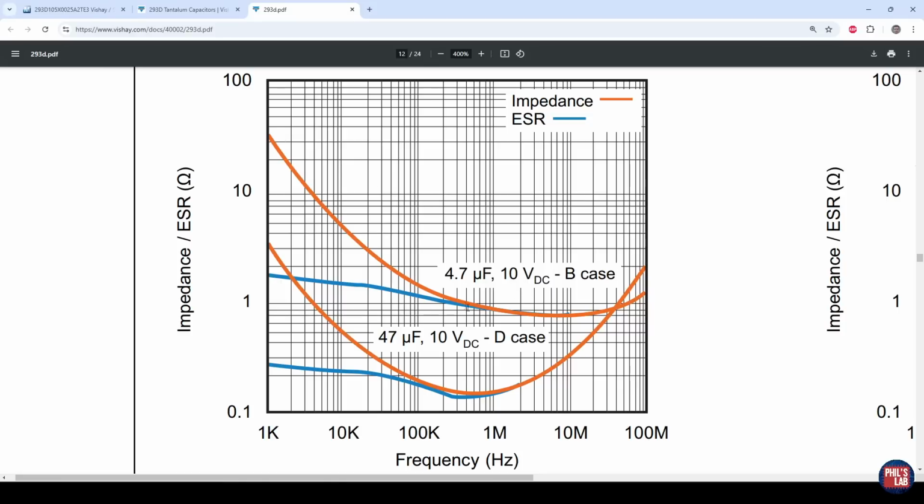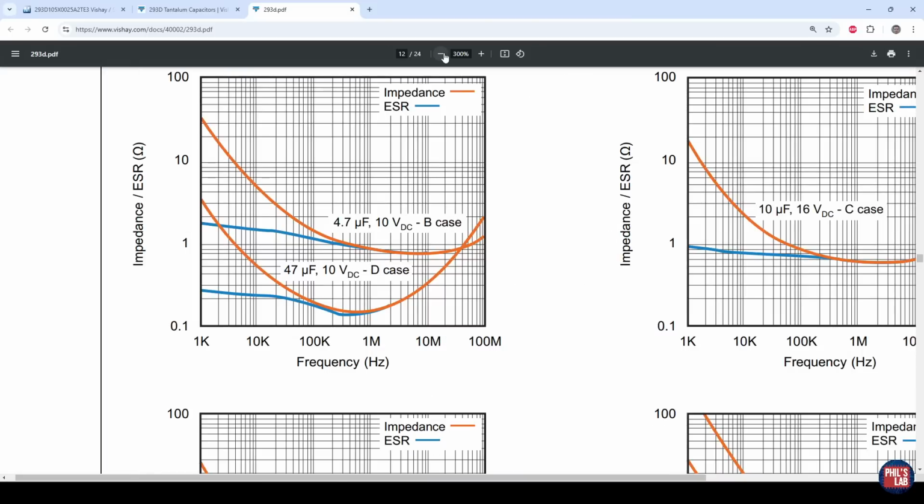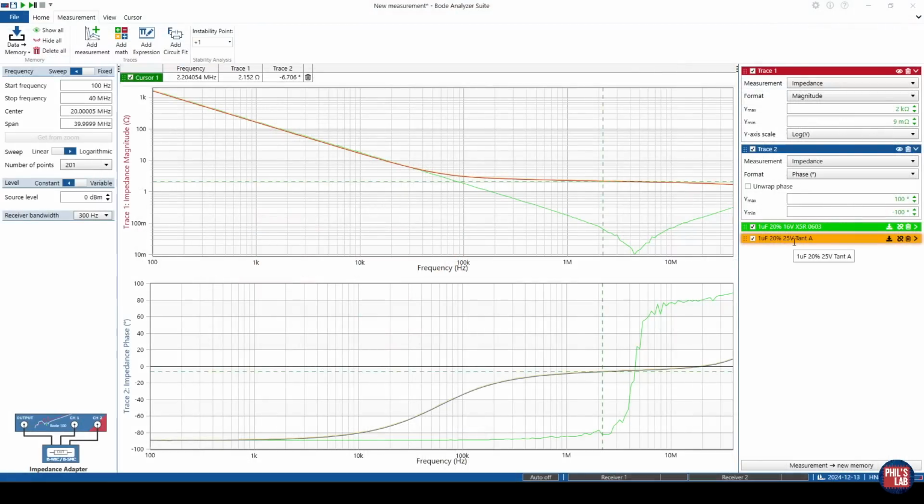we can see this also has a rather flat ESR response in the range of about 1 to 2 ohms, all the way up to about 50 megahertz. Only then the ESL starts taking over with this ramp up after that frequency. So that's where the ESL takes over, otherwise a very flat ESR band, and before that, that rather narrow capacitive region. So that's nice that this measurement somewhat aligns with what the datasheet is showing, at least for a very similar part. And now let's move over to the aluminium electrolytic SMD capacitor.